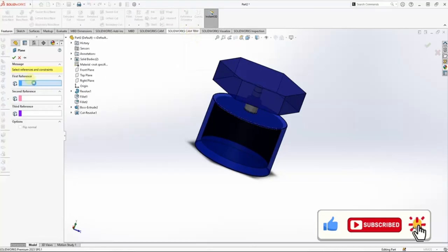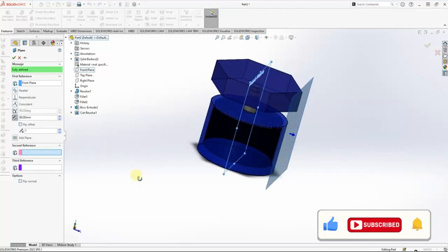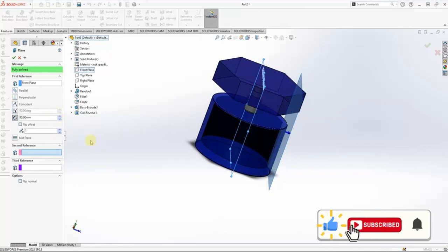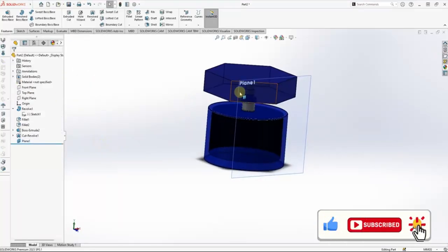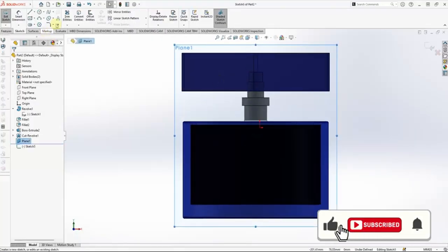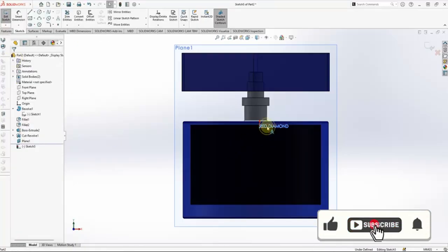Reference geometry, plane. The reference geometry is going to be the front plane. And the offset distance is going to be, okay, that's 90. I think that's exactly right on the surface. Say okay. Now, on this particular front plane, click sketch. And you can now write your letters on it. So Red Diamond, just like I did earlier, and make it italic. You can change your text or whatever. Now pull it here, and exit sketch.